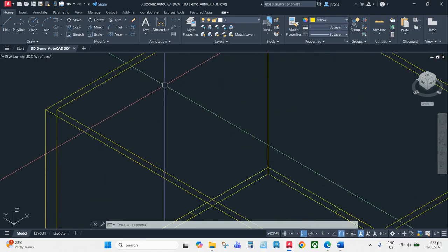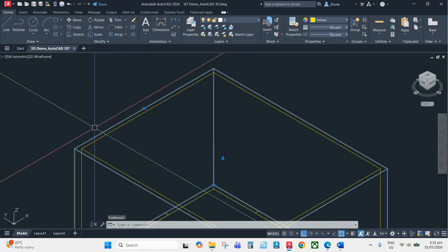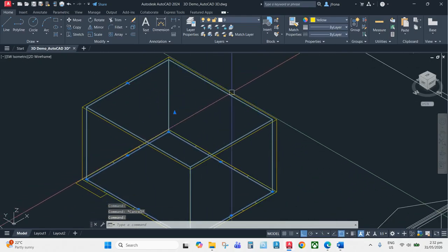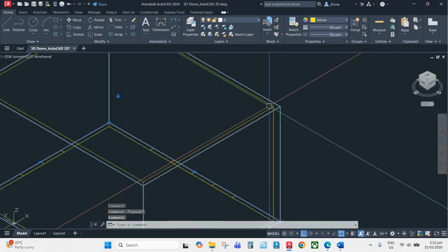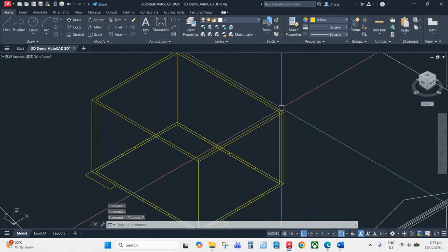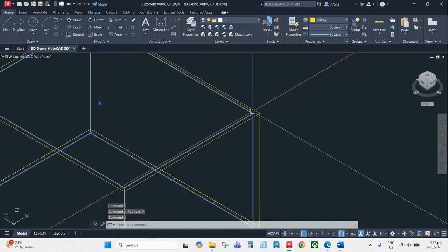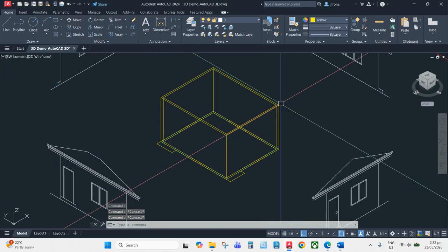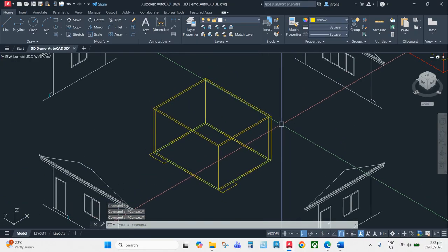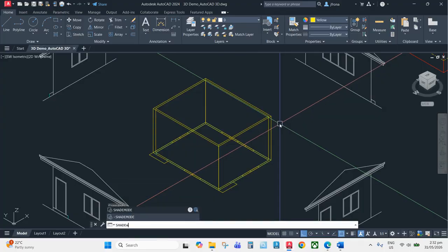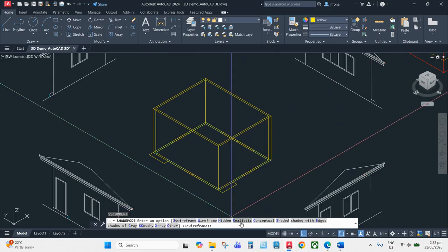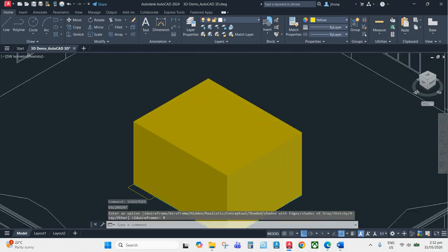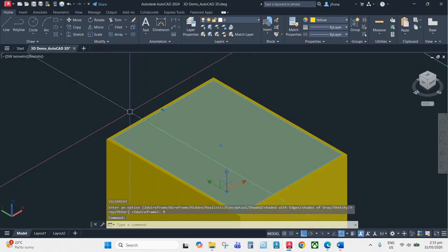So since we now have the volume for the exterior wall and the volume for the interior wall, these are separate objects because this one is one rectangle and this one is another rectangle. When you extrude them, they're going to be two separate volumes. So when you check them in your shade mode, and for example you select realistic or R, you're going to see two objects.